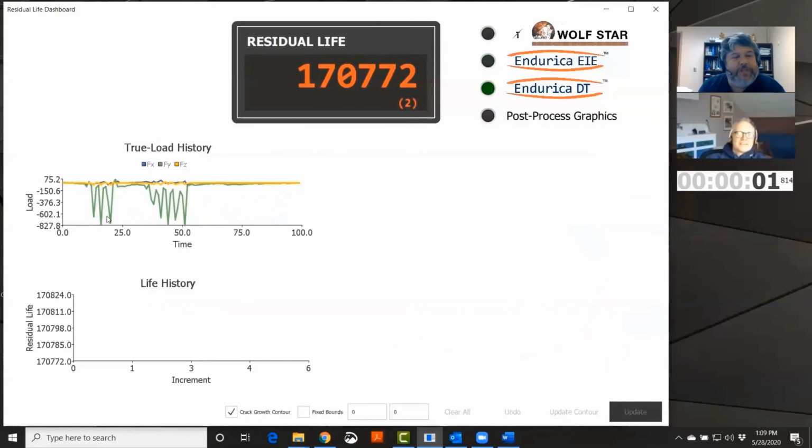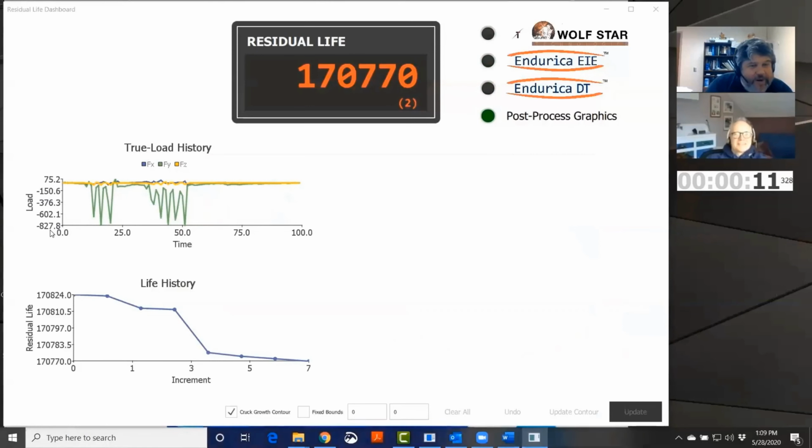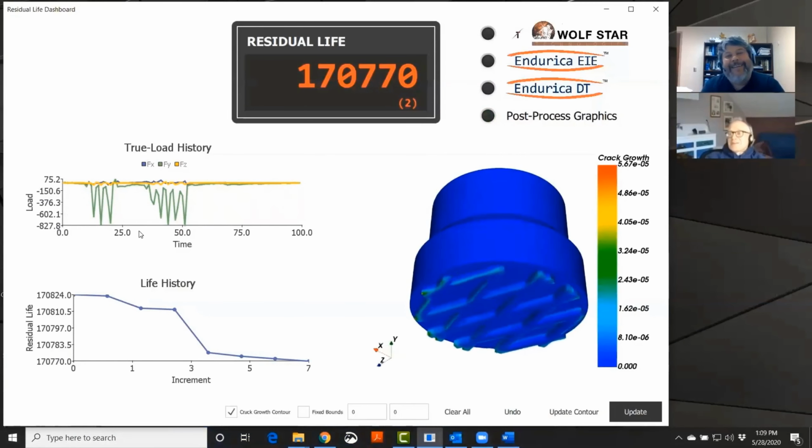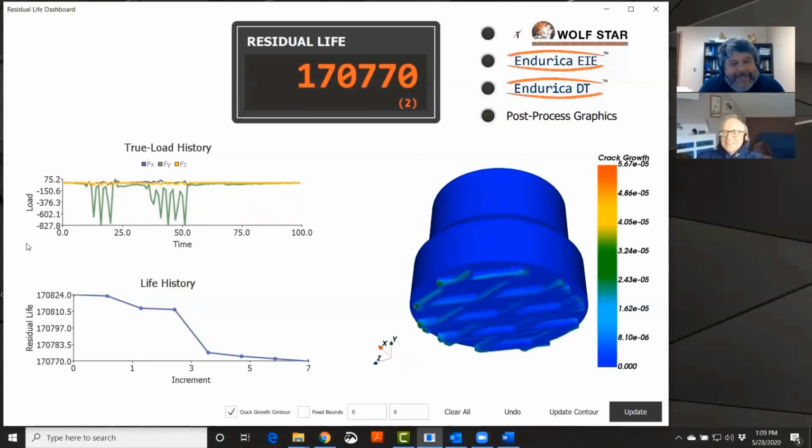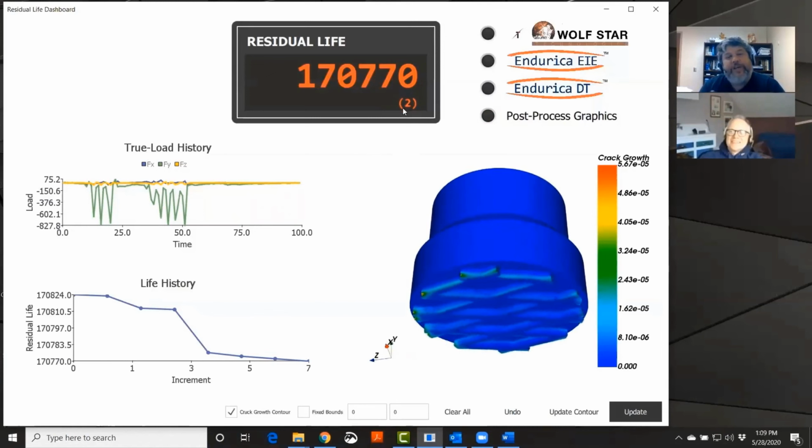There's your first jump. You got 1, 2, 3, 4, 5, 6, 7, 8 jumps. None of these jumps were up to the full load, right? So at most you've got 828 newtons of downforce. So you're kind of lightweight compared to the standard. I don't weigh 250 pounds. Taking small jumps, little bunny hops. Yeah. So in all, that decremented the residual life by 2 standard jumps.